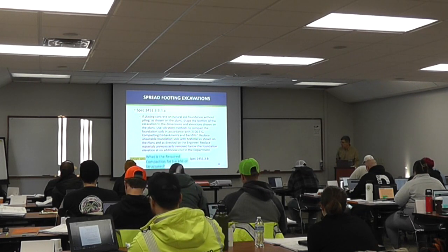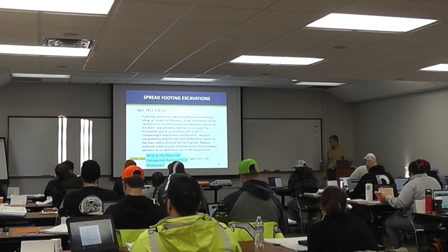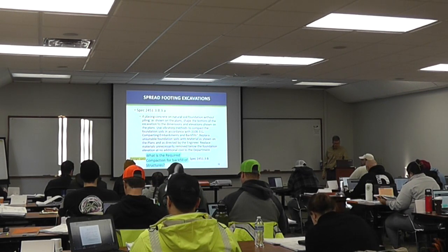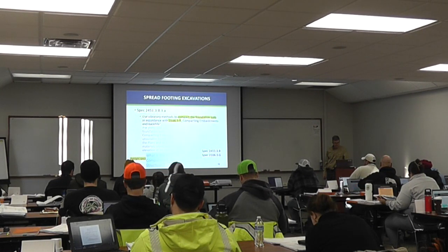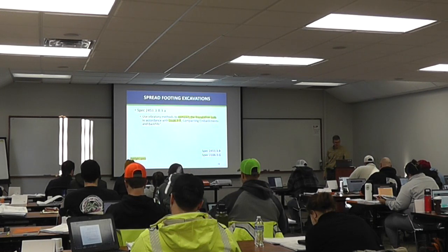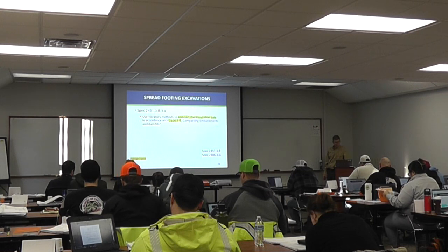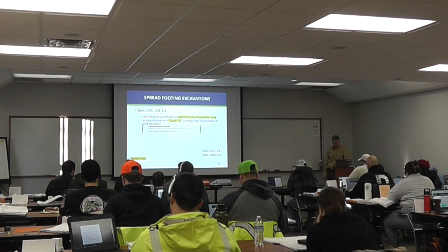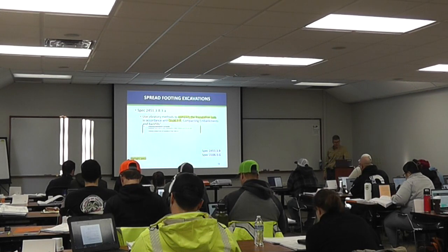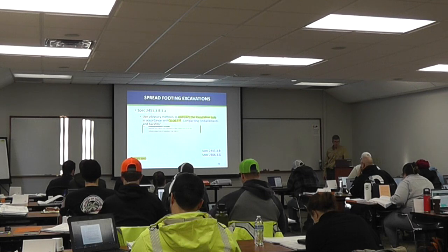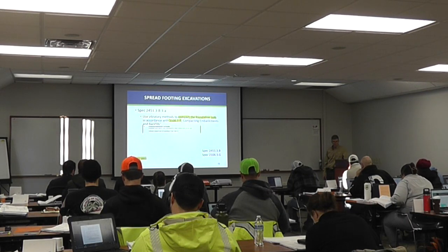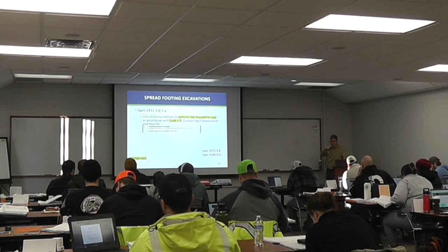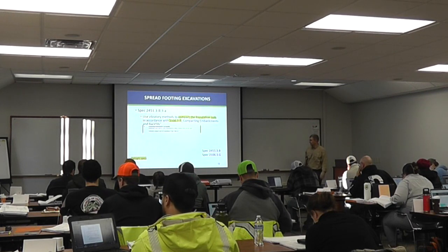But among the things we want to realize is that it's turning us to 2106.3G. So that brings us to the question, what is the required compaction for backfill of structures? And how are we going to find that? So when it says use vibratory methods to compact foundation soils according to 2106, who can tell me what is the requirement to compact per 2106? 100%. 100, better 100%.